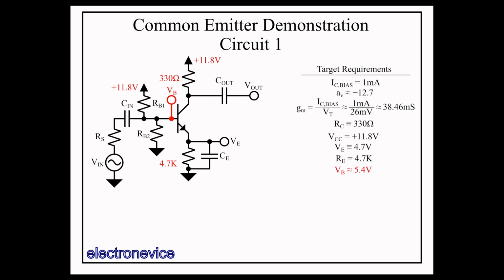Before we set the values for the biasing resistors, we need to have a better understanding of R pi and RS. RS is going to be around 50 ohms, since I'm going to just use my function generator, which has a 50 ohm output resistance. And the transistor we're using is a 2N3904, which at 1 milliamp collector current has a beta that ranges from 70 to 300 at room temperature, though the 300 number is taken from a more optimal collector current since the datasheet doesn't indicate a maximum value for the 1 milliamp collector current. This translates to an R pi of from about 1.82K to 7.8K.